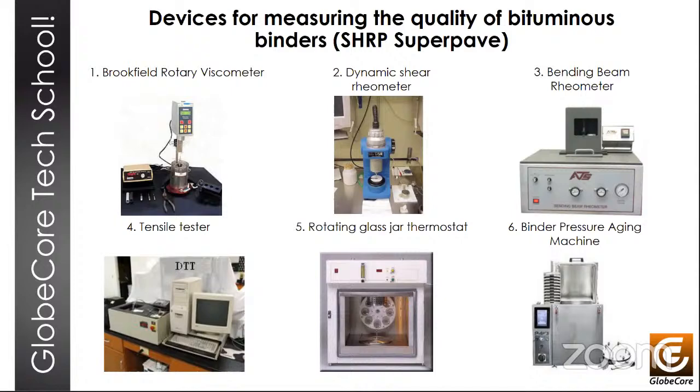In this regard, one of the criteria for assessing crack resistance is their deformability at low temperatures. As a result of this test, the temperature is determined at which the specimen tested in tension at a speed of 1 millimeter per minute breaks at a certain deformation, and the deformation must be at least 1%. So for such tests, it's very important to have a capacity to measure this deformation very accurately. So mostly we use laser micrometers for that. And the temperature in this test is maintained with high accuracy of plus or minus 0.1 degrees centigrade.